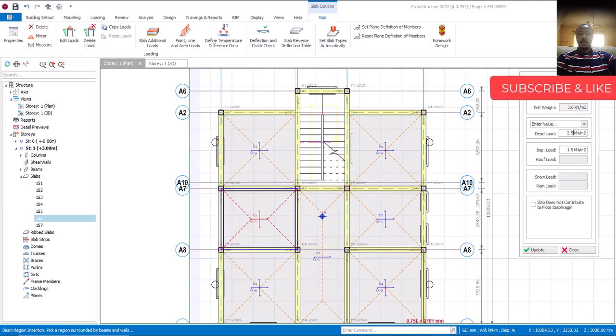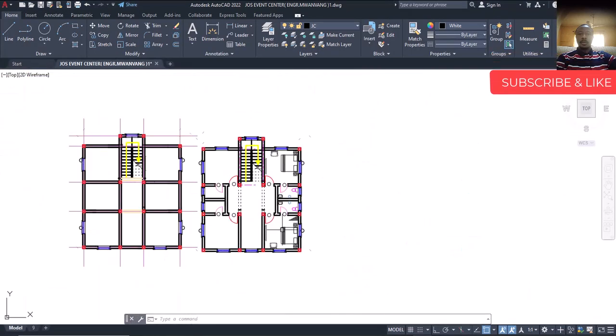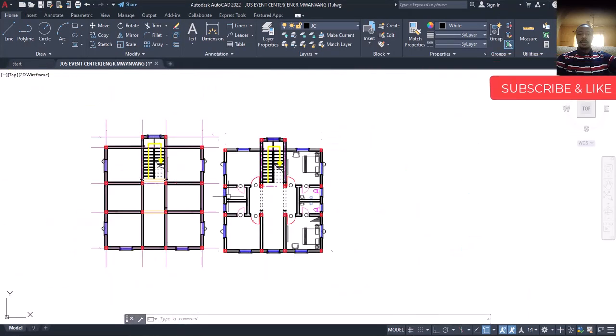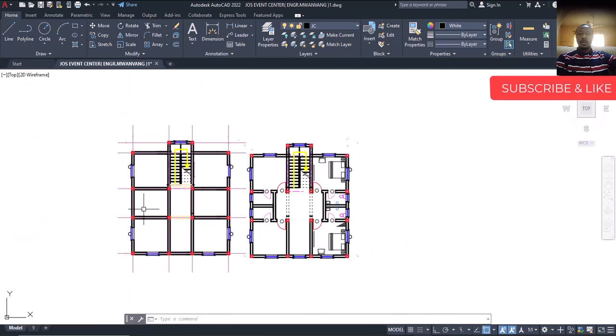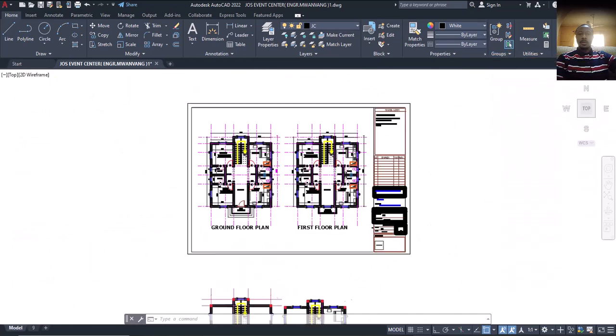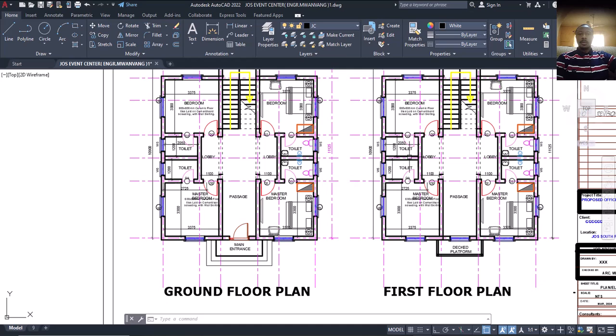This particular wall load here, this wall load that we have here, because if you notice, this one now is resting on this slab. This particular one, we have it on the ground, and we also have it at the top. Even though the one on the ground can support this one, we don't design based on that. Our slab should be able to stand without any support.